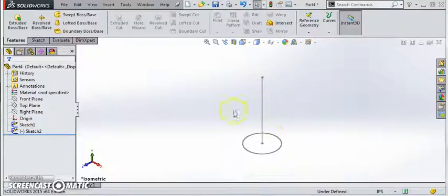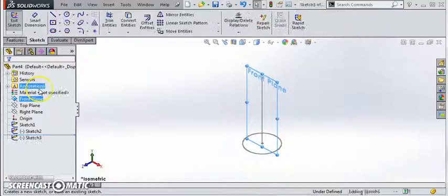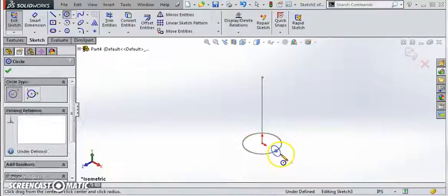Now we need to create our third sketch that is also going to intersect the original sketch, so it also can be on the front plane. You need to keep this separate from the sketch we just created for this to work appropriately. So we'll create that third sketch, and now this is going to be the profile of our coil spring. Create a small circle right there.